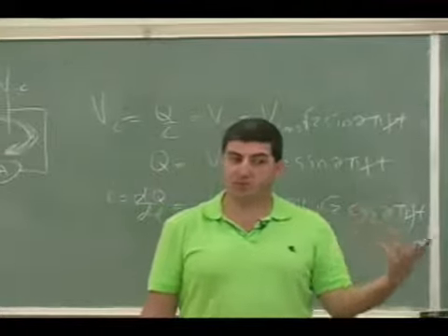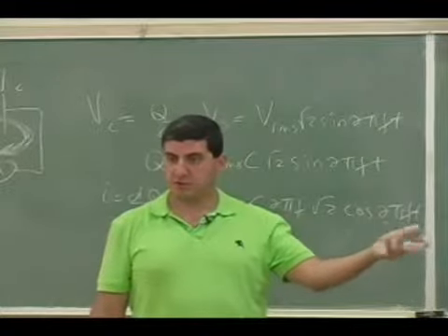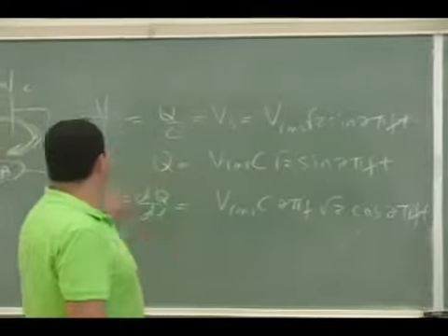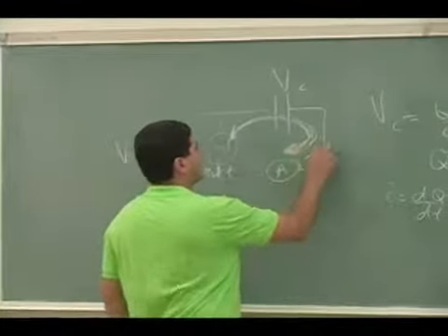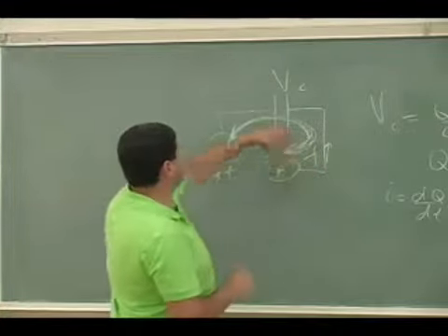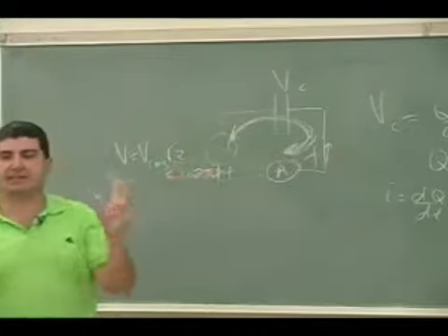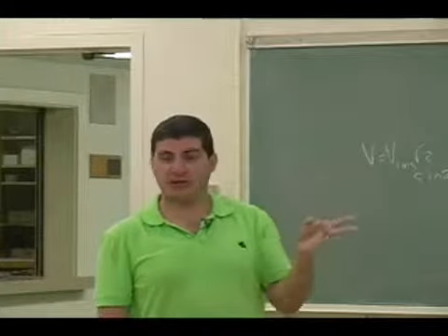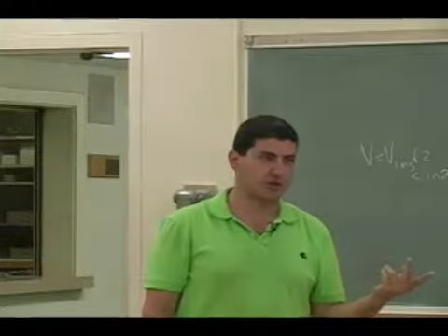So for the capacitor to resist the battery, you've got to build up charge on it in order for it to act like an opposite battery. But if the frequency is high, the current's going that way, current's going back, forward, back, you're not giving the capacitor enough time, enough chance to build up charge in any one direction. Before it's charged, you're switching the charge on it.